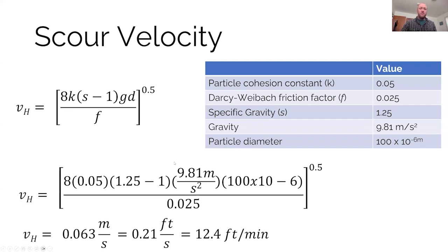So that means for the velocity of that water to flow through something, and instead of depositing sediment, what's the velocity where it's actually going to start picking things up and taking it with it. So that's, of course, not what we want when we're trying to have things settle out. But we want to have a scouring velocity in our collection system, of course, because we don't want sediment to fall out in our collection system. We want it to all settle out in our treatment process. So we want to make sure that our water is not moving too fast in our treatment process to have scouring.